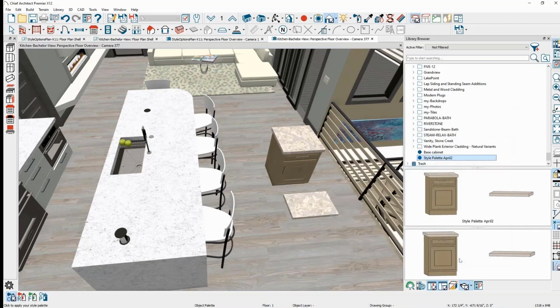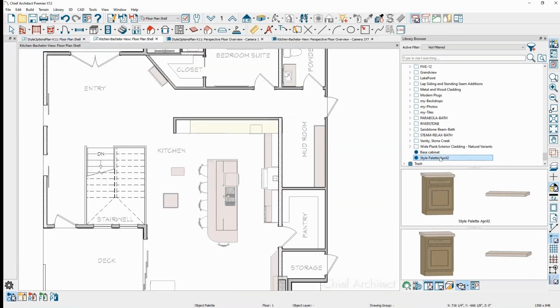Okay, so the marquee select has to be done in your floor plan view. Let me go over to the floor plan here. Click on the style palette, come over and change your scoping tool. Again, this is only available in the floor plan view. Again, it's probably difficult to see my screen unless you zoom, but it says marquee mode. So once I'm in marquee mode, I'm going to come down here and I'm going to hold my left mouse button down, click and drag over the island.